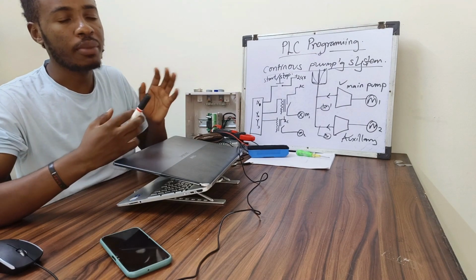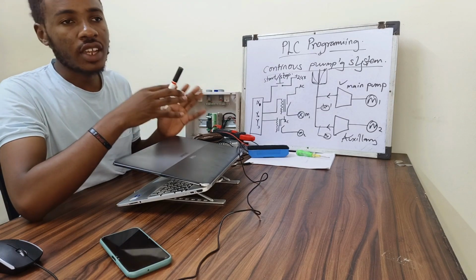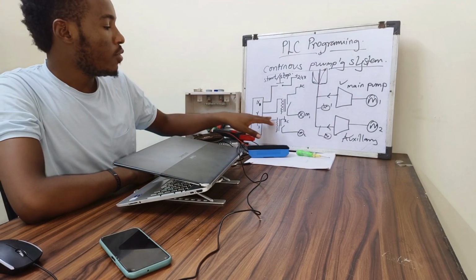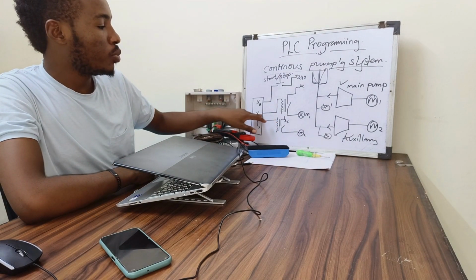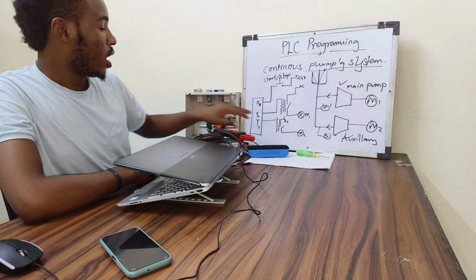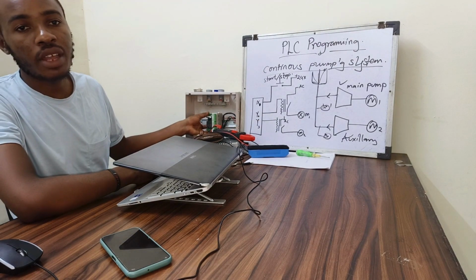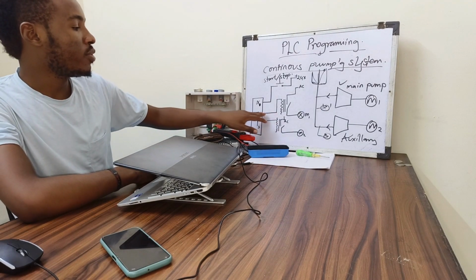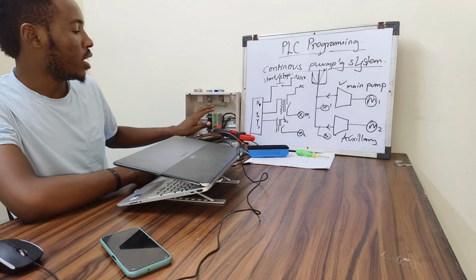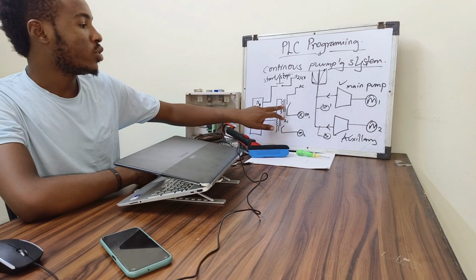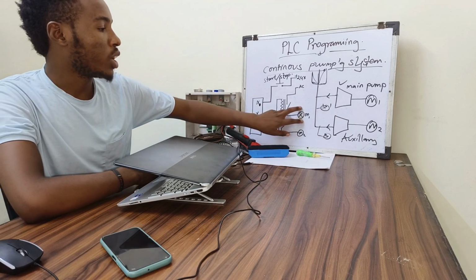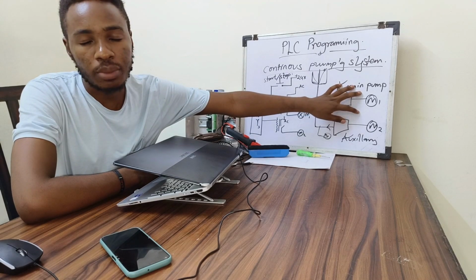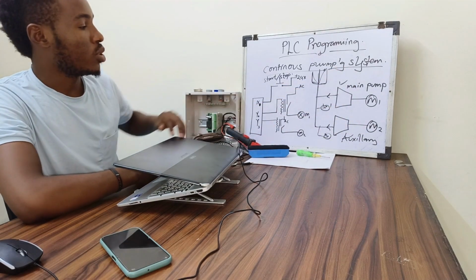Like, you have the primary, the control circuit, and then the active circuit, the power circuit. So in that, you have this output from the PLC coming to the relay. Here, I have the relay board. All this will be DC. So the output coming from the PLC goes to the relay, and from the relay we can switch on and off the contactor that is going to be connected to the motor. So this is how the entire system is going to be working.